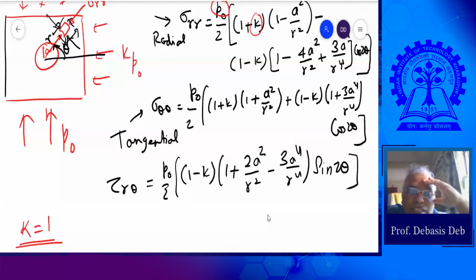That is also a principal plane, that I agree. Mu equal to 0.5, so the stresses will be equal. No. Do not go by that. This K also has many other things, not only mu by 1 minus mu. That may have a tectonic part, that may have many other frozen stress parts.